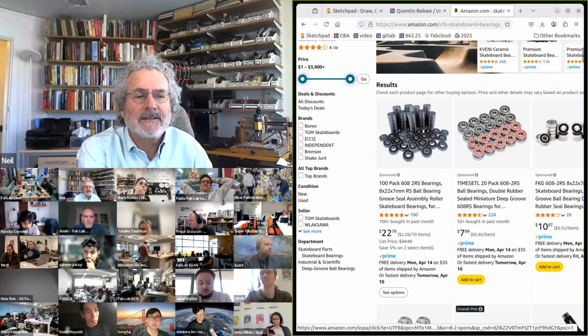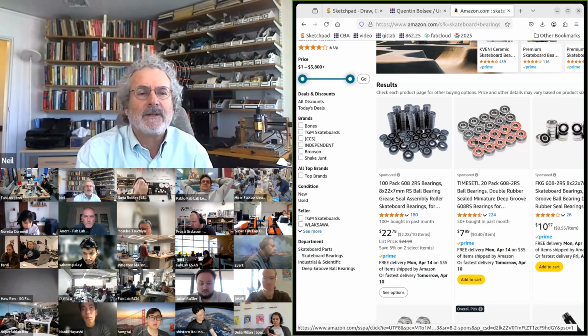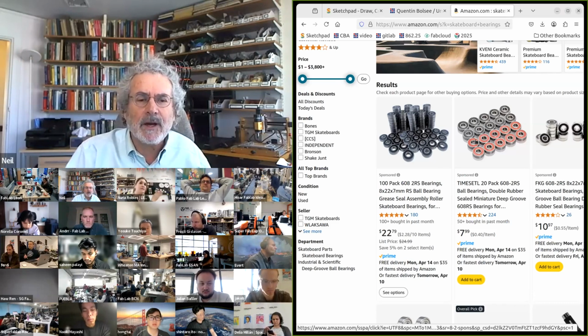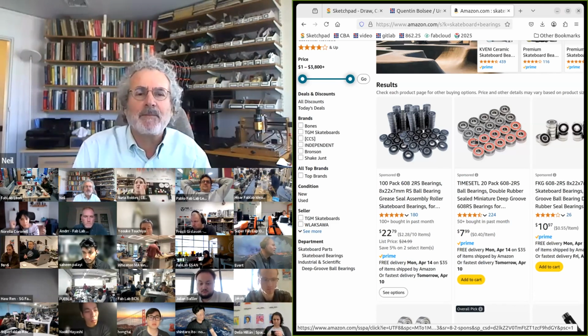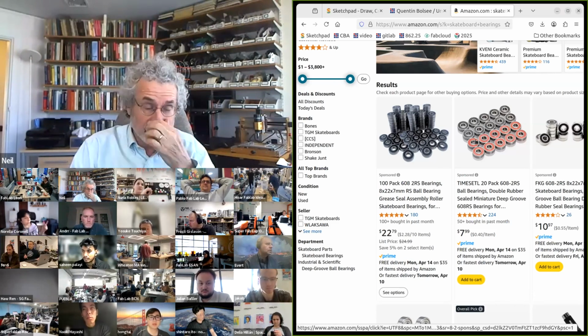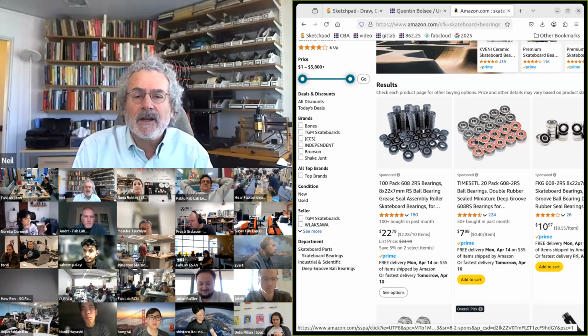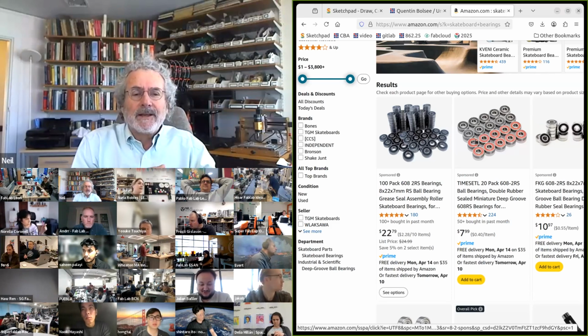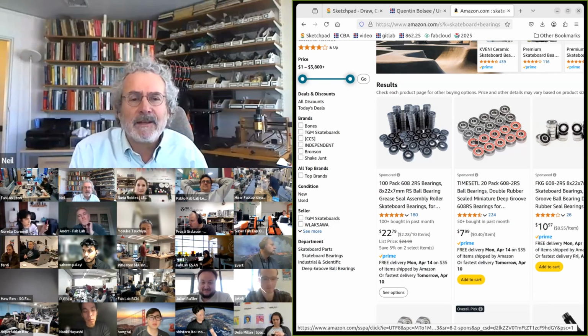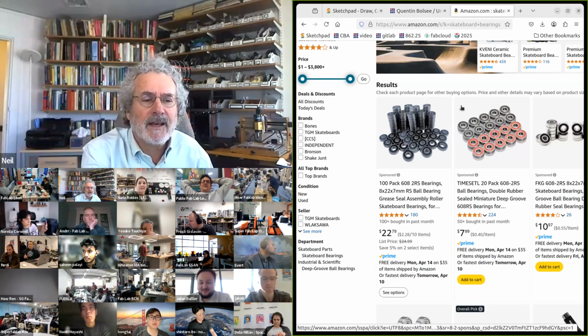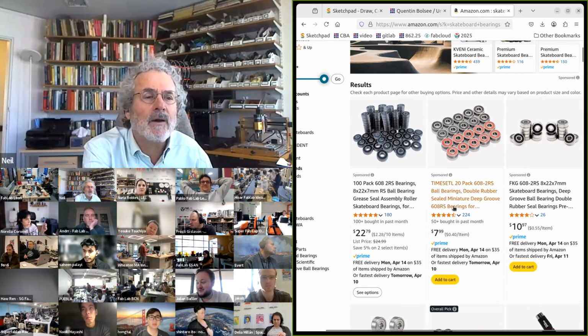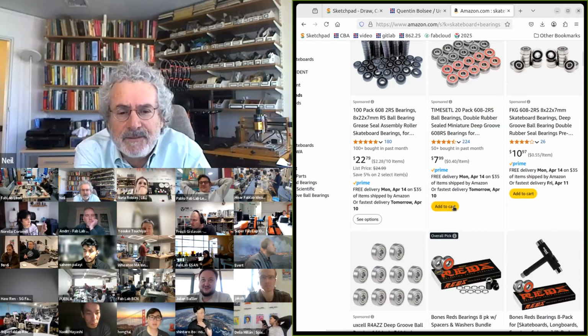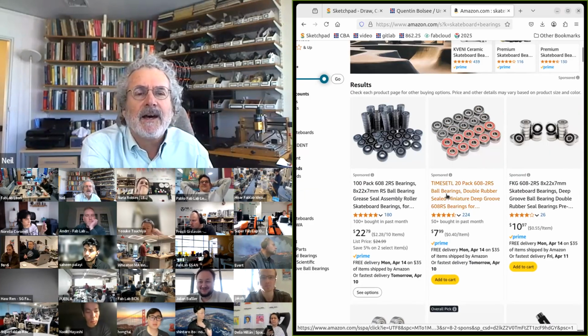These sort of bearings have come way down in cost. So they're colloquially called skateboard bearings, but they're used for many other things. So these are rotary bearings that are down to like $1 each. Now you need to be a little bit cautious because the quality of them varies very significantly.